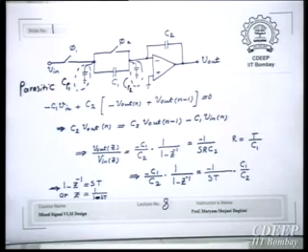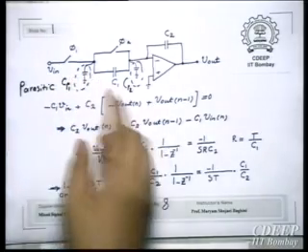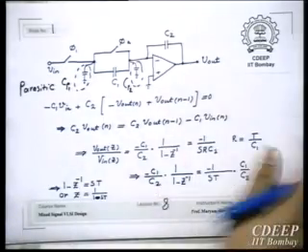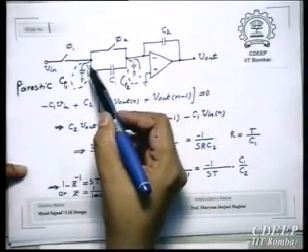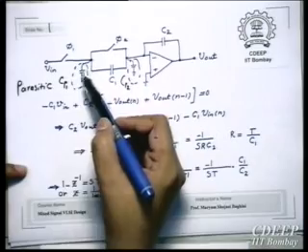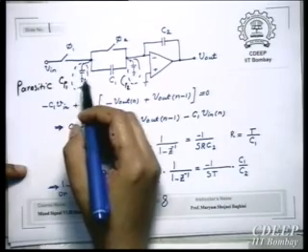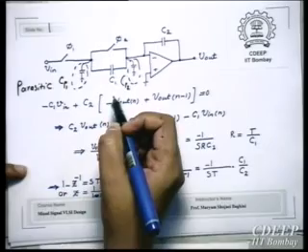So what happens is, for example in phase phi 1, we want the input to be here. Now of course look at this circuit, essentially how it will behave. We have some parasitic capacitance here, and of course this will be connected to Vin, this will get charged, and we have phi 2 when C1 is getting discharged.